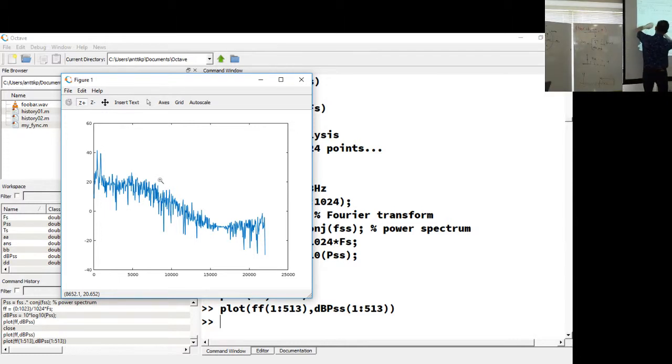The low-pass filter part actually shows up here. So without the low-pass filter, we would have the spectrum just continuing like that. You can try it yourself if you don't believe me. But anyways, that's after the filtering. We have suppressed some of this noise on the non-interesting part of the spectrum, and we haven't touched much actually these tones. Good. So that's a simple signal spectrum.